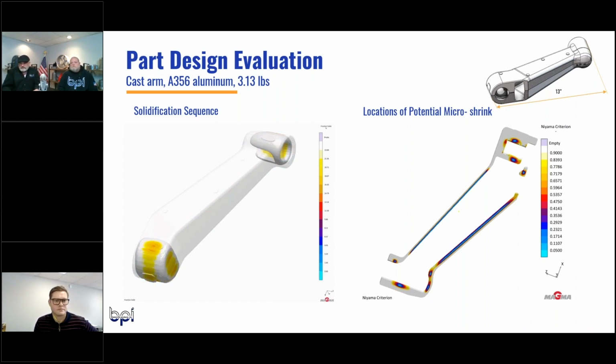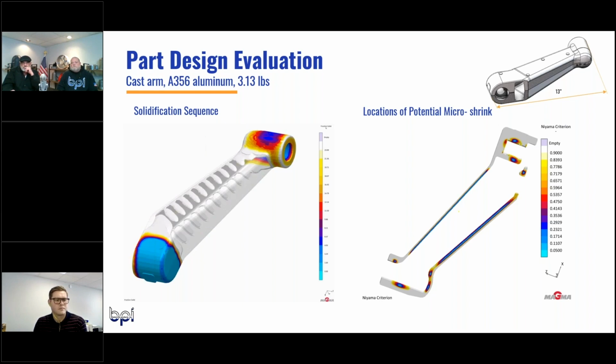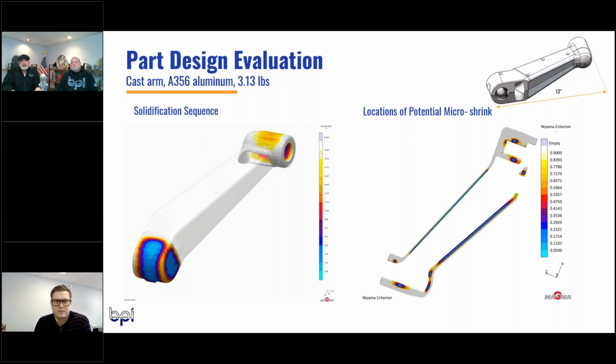It's a thermal criterion that looks at the relationship between the cooling rates and thermal gradients, and it's very well established and published in the literature. And the criterion is specific to a set of alloys. In this case, it's unique to alloy groups that are solidifying in a dendritic fashion with longer freezing ranges, which is what aluminums and steels would do. It's widely used for steels.